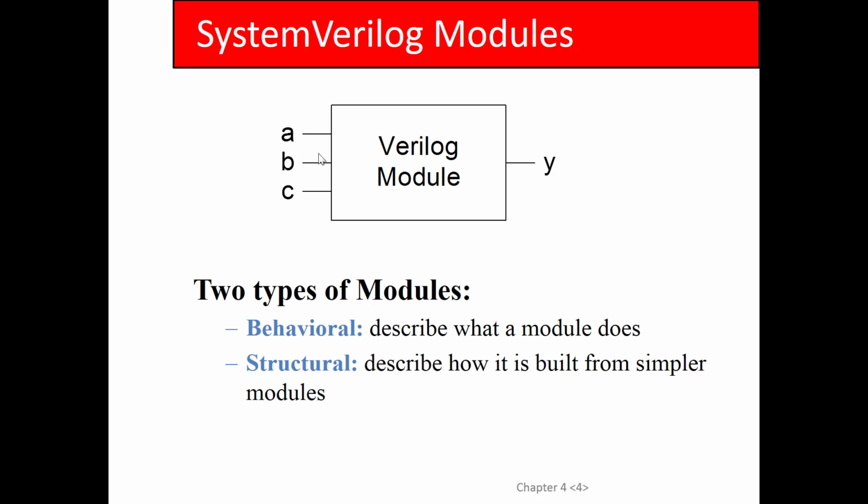I stopped doing that though because of a few reasons. One of which was if you got an error in the synthesis or simulation, it would refer back to a line number in the HDL, which you've never seen because you didn't write it. You just designed a schematic and the HDL got generated.